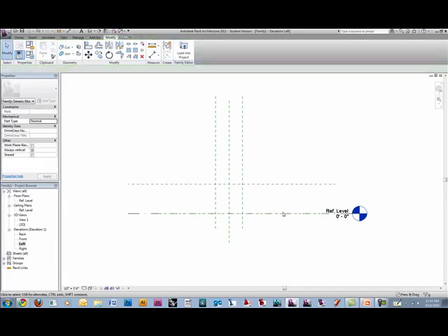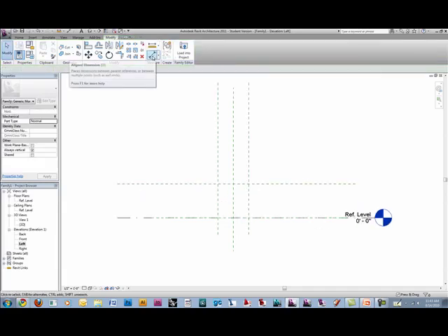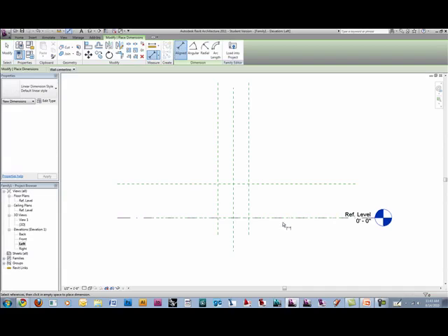Escape key. Alright, so we're going to also give this a constraint. We don't have to get this in an equal constraint because we want it to touch the reference level. Whatever we're snapping it to, we want it to land on top of it. If you want it to land below it, you would put stuff below. You draw your geometry below this as well.